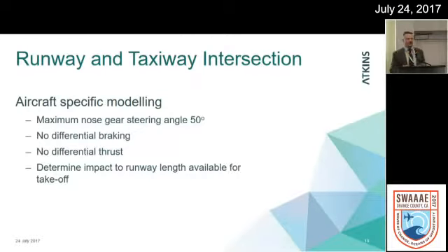So when we do aircraft-specific modeling, the Advisory Circular 13A has very specific criteria that are used. We cannot have a maximum nose gear steering angle of greater than 50 degrees. We don't want to overstress the nose gear of the aircraft making the turn. We don't want differential braking, and we don't want differential thrust. Honestly, we did do a model that locked up the left differential braking. We did full thrust on one side, reverse thrust on the other, just to see what the aircraft would do. But we didn't share that because it was a little bit aggressive.